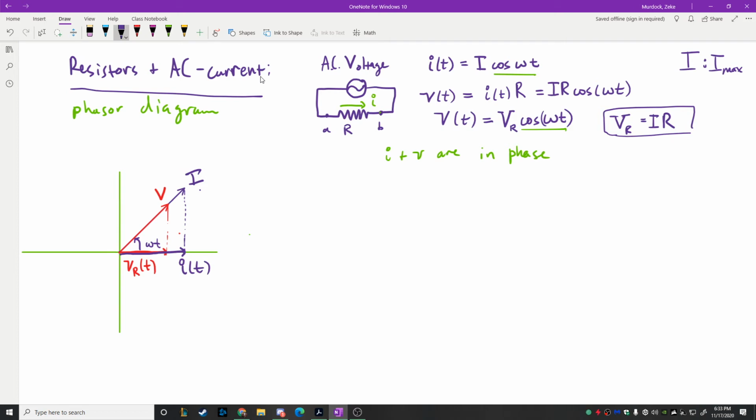And we know to put them on one another because they are in phase. That's exactly right. Yep. They are in phase with each other. Now, one thing that you're going to notice as we go forward, the x-axis is always going to look the same, kind of. But this is the only case that we're going to see today where the current and the voltage phasors are in phase. Okay? It's the only case where they're in phase with each other. The other two, they're not going to be in phase.